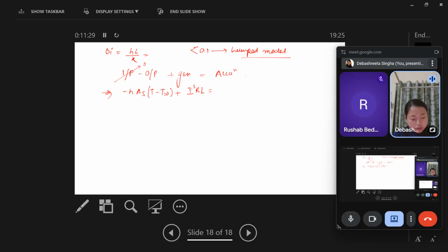So they have already given the rho mCp by T. So mass is given as rho V Cp dT by dt. So output is the convection term. Generation is the current generated, I mean the heat generated due to the current. Then accumulation is this storage part, the energy storage part.